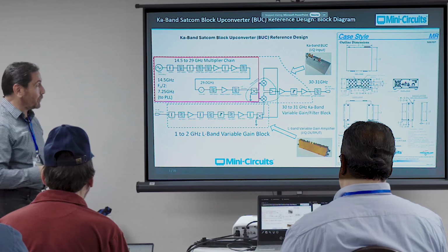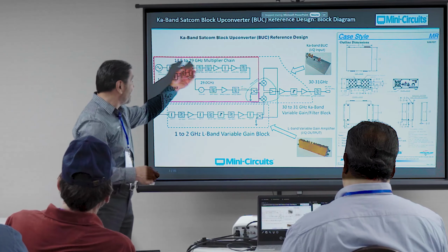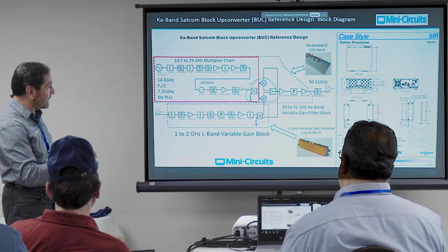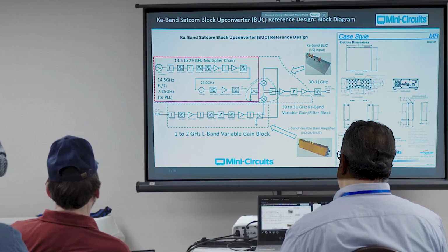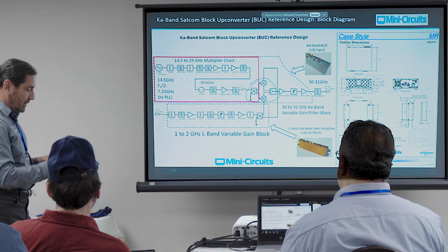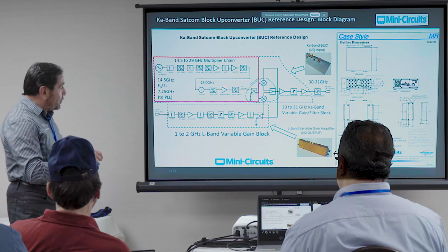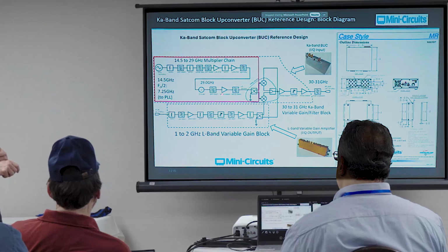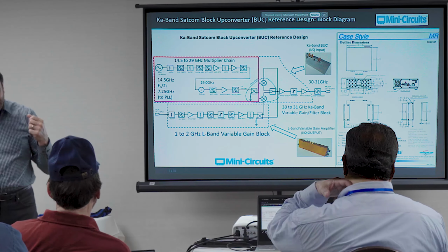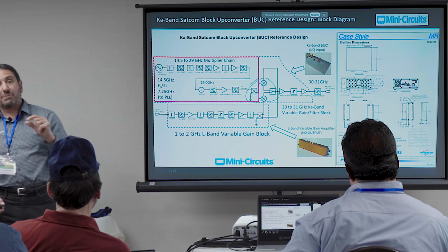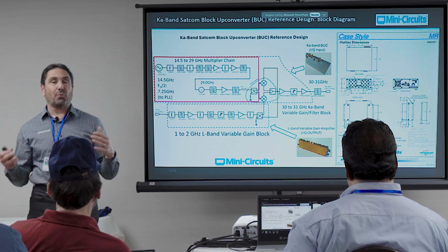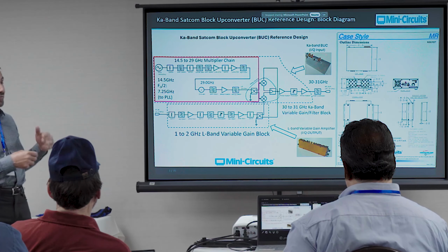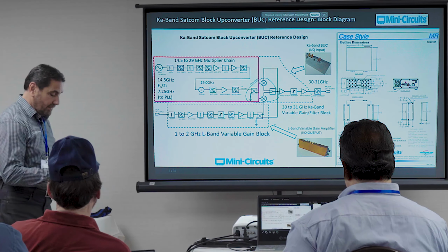And that's very important when you're doing something like this, where you don't want this stuff feeding back into the VCO. Then we're going to talk about, in gory detail, cascading these two amplifiers for minimum degradation to additive phase noise. We'll look at the final output here and how this section contributes as well. Because as you go higher in frequency, you'll find that the gate length gets smaller and smaller on some of these pHEMT amplifiers. And as that happens, your 1/f noise degrades. So you have to be careful, even back here, that you're not affecting the overall phase noise performance.